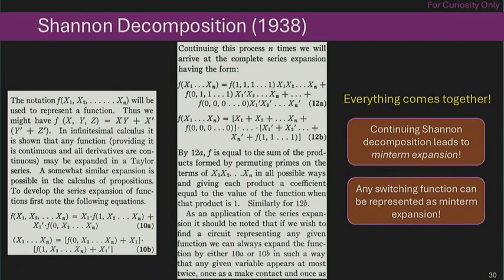And this is Shannon's work on his decomposition theorem from that paper in 1938. But it's surprisingly readable. You have a Boolean expression involving a bunch of variables. You can set that variable to 1, like a constant 1, to simplify the implementation, and then multiply that result with the corresponding variable. Then set it to 0, right? Multiply it with the complement of the variable. And that's essentially how we represent the output behavior of a mux, a way to decompose a function into individually smaller subfunctions. So I also uploaded this document to Canvas. If you want, you can just look at it for fun.